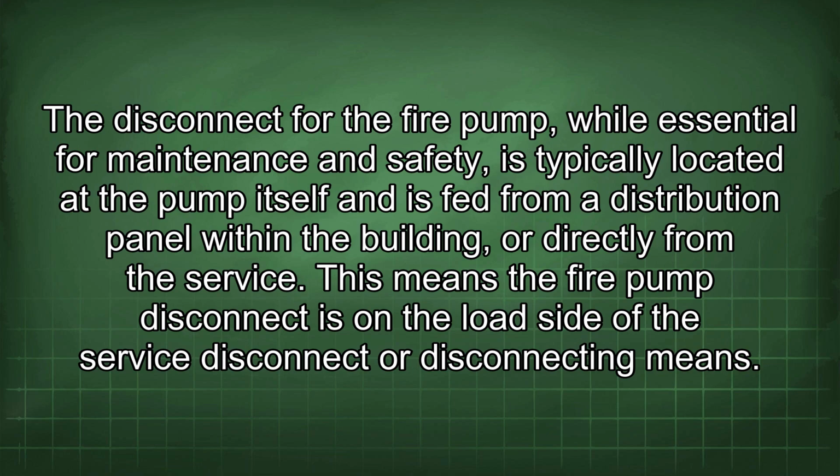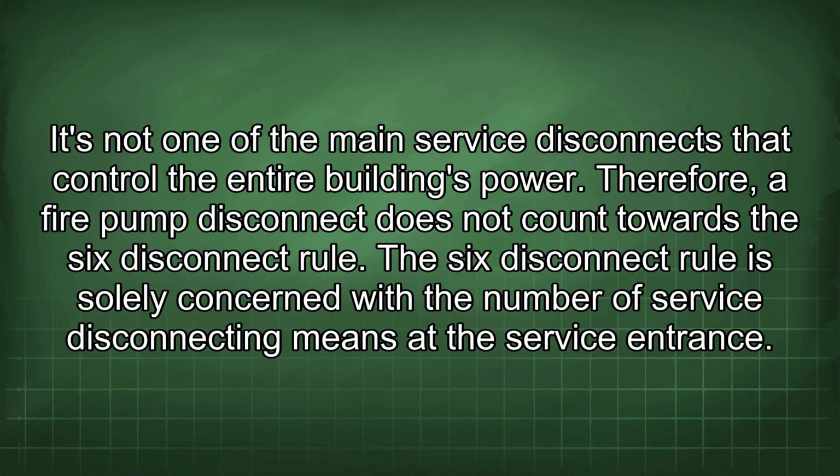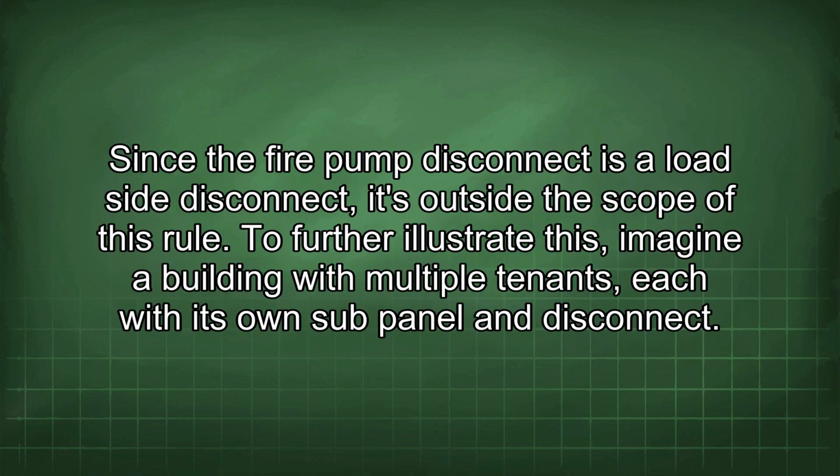This means the fire pump disconnect is on the load side of the service disconnect or disconnecting means. It's not one of the main service disconnects that control the entire building's power. Therefore, a fire pump disconnect does not count towards the 6 disconnect rule. The 6 disconnect rule is solely concerned with the number of service disconnecting means at the service entrance. Since the fire pump disconnect is a load side disconnect, it's outside the scope of this rule.